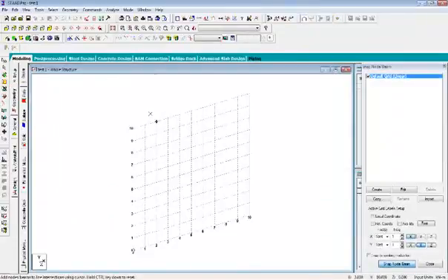One thing about file naming: I would say never name a file structure1, because by default the name is structure1. If you save a file, do some work on structure1, and again go on doing it as structure1, the previous file will be replaced by the new one. So all the work you have done will be of no use at the end.